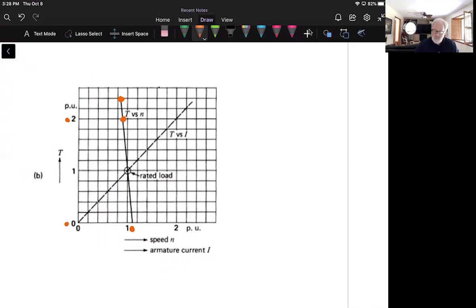All right, so what does that mean? Let's put it in plain English: in a shunt configured DC motor, there is not much variance in the speed from full load to no load, right? The speed doesn't change very much. What we're saying again is 10 to 15%, even less for larger motors.